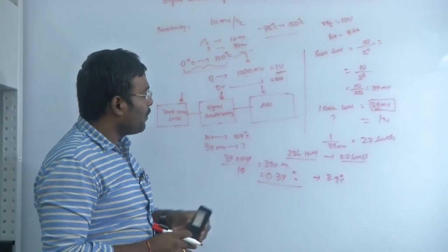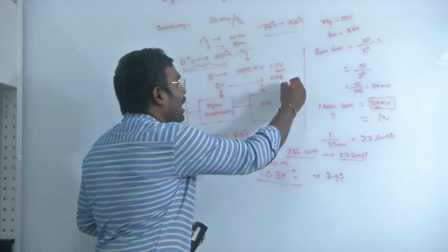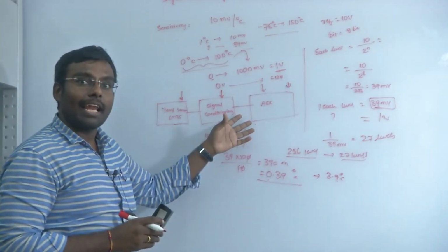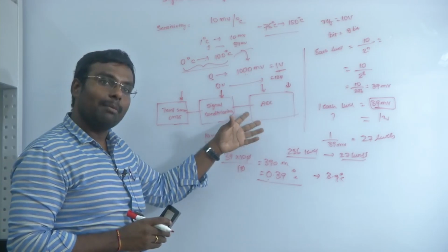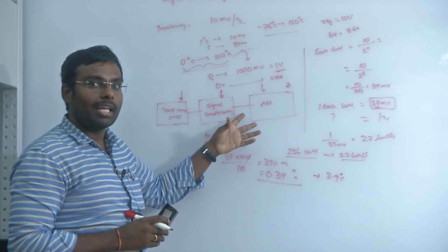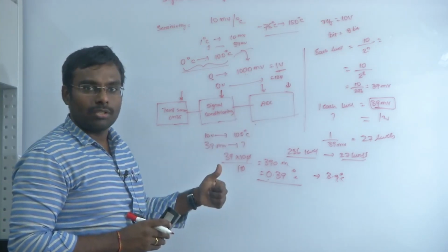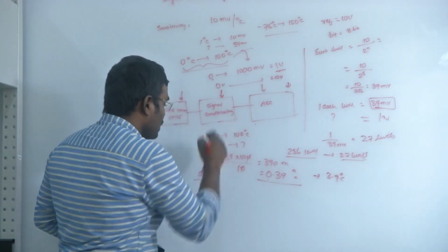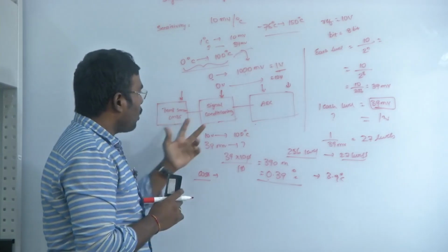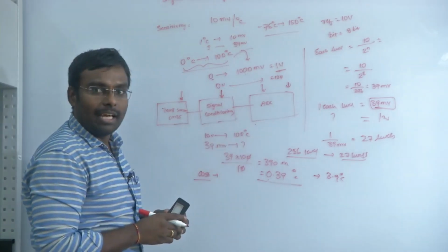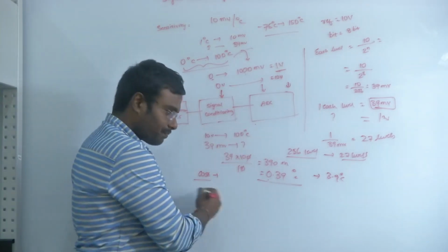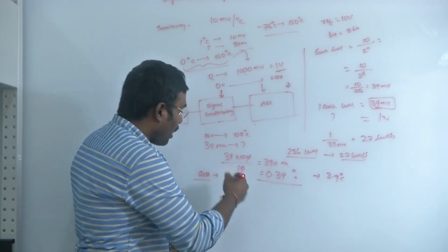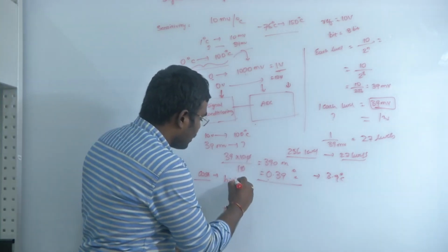You may ask, would it not be useful to go with a higher bit ADC? Yes, it can also be achieved with an even higher bit ADC, but the problem with higher bit ADCs is cost. So, at a low cost, by using a simple operational amplifier between the output of the sensor and the input side of an ADC, we can achieve higher resolution.